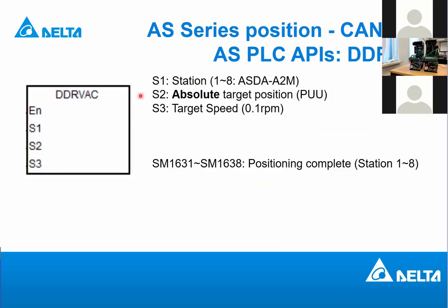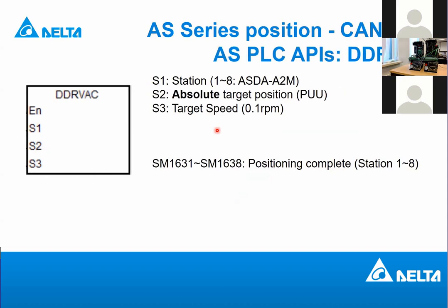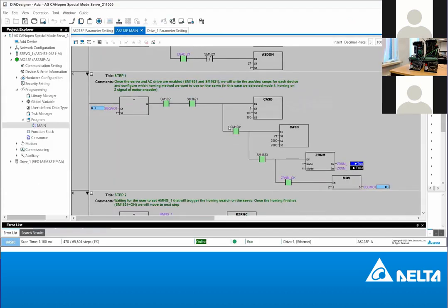And then let's continue with the testing. Now we have already done the move incrementer. With this move incrementer, you move the drive to the position you have specified. It always increments whenever you trigger the incrementer command. The next movement you can make is absolute positioning, absolute movement. And this is the instruction, DD arrow V absolute. When the absolute motion is completed, this flag also gives you feedback that the absolute movement has been initiated.